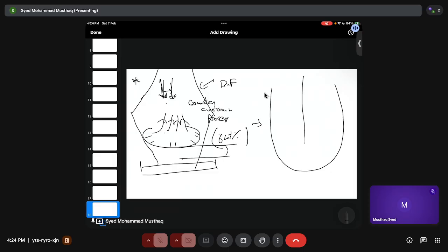So what you do is you just blow oxygen into this steel. People might ask, you just reduced it, so why are you again oxidizing? At that temperature, the oxides are not very stable, and also the impurities will oxidize first rather than your steel melt. Then you blow oxygen to an extent that you form a froth, and there are different things that happen.